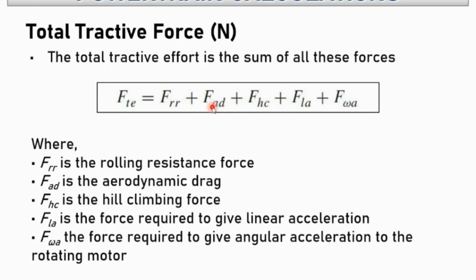Air density, speed of the vehicle. Oh yeah, you're right. Speed of the vehicle is a very critical parameter for the aerodynamic drag calculation. Okay, air density is pretty much going to be constant. Probably when we are driving to a hill station, it's going to be slightly different. But considering at least our case, we are going to operate it normally. So probably the density of air would be a constant.